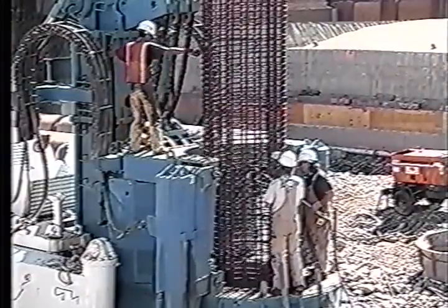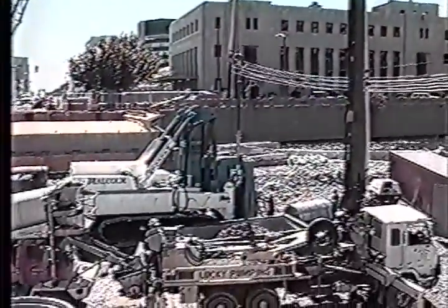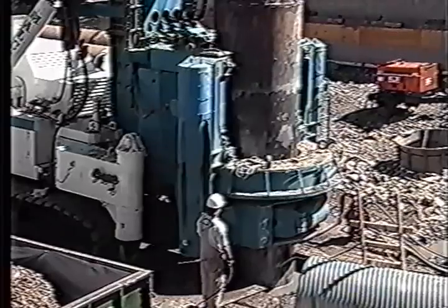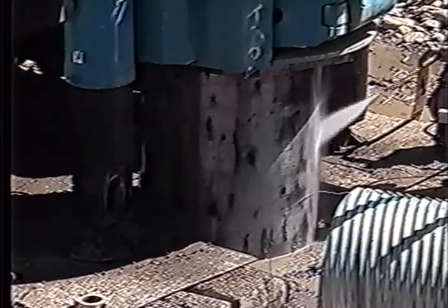A 60-foot rebar cage is lifted and carefully placed in the hole by trained personnel. Concrete is placed in the hole by a pump truck. The casing sections are easily removed. The XL rotator has the capability to drill over 250 feet in depth using the fully cased method. It can also work continuously around the clock, going through contaminated materials.